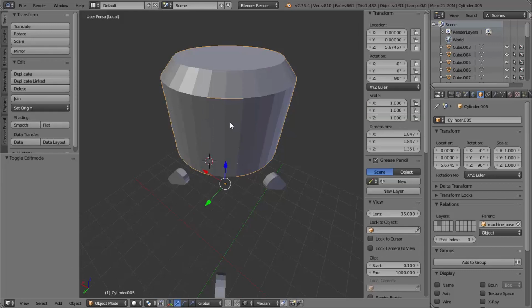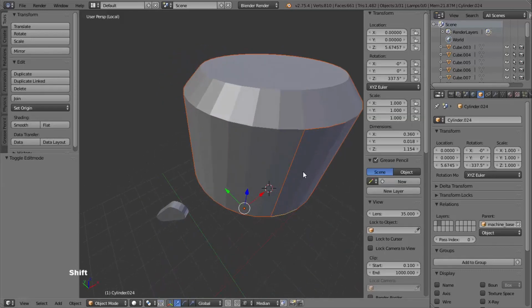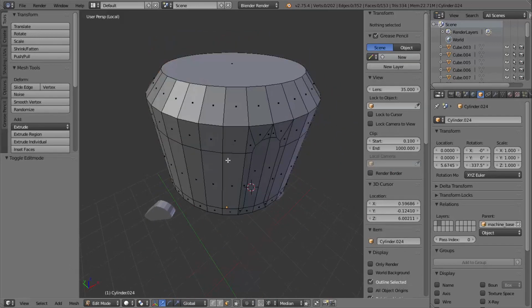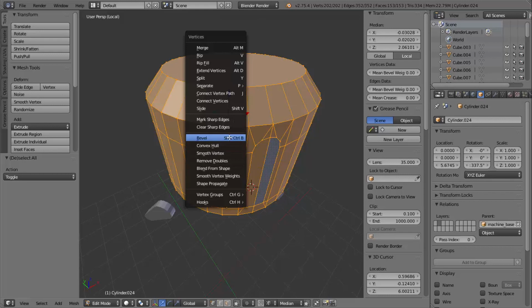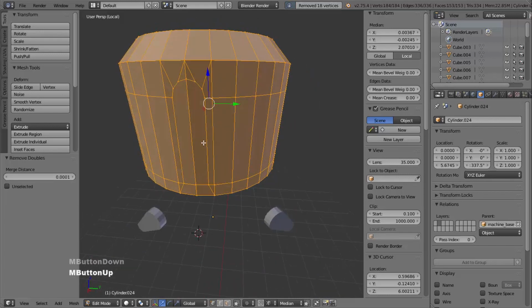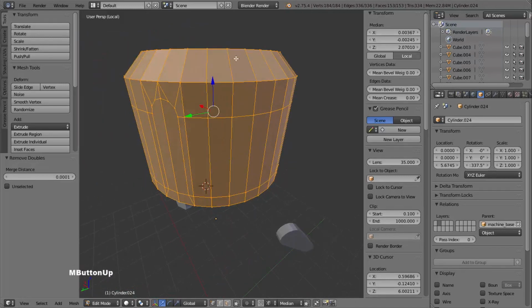And then going into object mode, if I shift select these two strips of geometry and then click the join button, I can go into edit mode and then Control Tab into vertex mode and select all of the vertices, and then I can press Control V for the vertex menu and then choose remove doubles. So now I have these three vertical grooves spaced appropriately in the object.